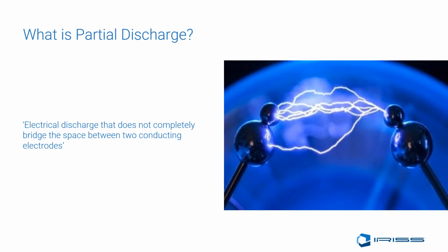Partial discharge activity inside metal-clad high-voltage gear includes small voltage impulses called TEV, or transient earth voltage, across the surface of the metal panels. TEV travels around the surface to the outside of the switchgear, where they can be picked up using externally placed partial discharge detection devices like the Sonos PD Alert.